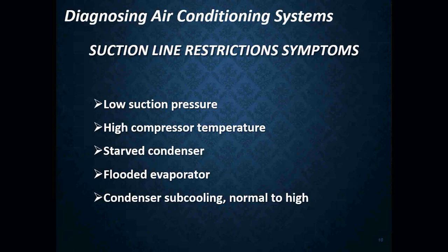condenser subcooling lets the technician know there is refrigerant in the system and that an undercharge of refrigerant can be ruled out. That's why it's really important to be sure that you're taking superheats and subcoolings. Make sure you take those readings. You have to know what is going on with the refrigerant flow. That's telling us whether or not the refrigerant is flowing freely through that system. It's telling us whether or not we have the correct refrigerant charge in that system. And if one of those is off, that is a telltale sign that we have a refrigerant issue.